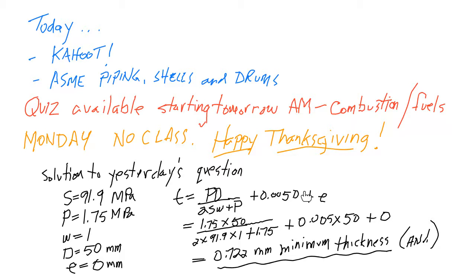Now, is that okay? Because somewhere we were looking and said that we needed to have a minimum thickness of 6 millimeters. So can we actually use a material that's like 3/4 of a millimeter thick? Is that okay? No. It's not okay. So are you suggesting that that tube has to be at least 6 millimeters thick? Yeah. Okay. This is the common misconception. The 6 millimeters only applies to plate. And this stuff isn't plate. This is tube. Okay, remember we looked at product forms.